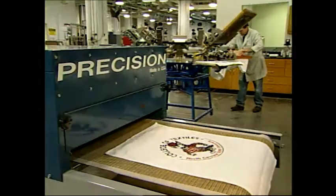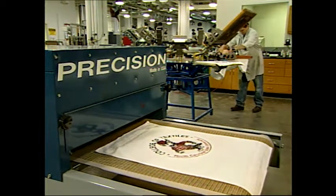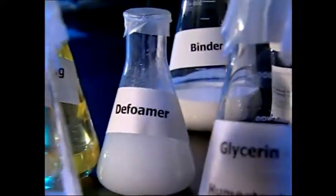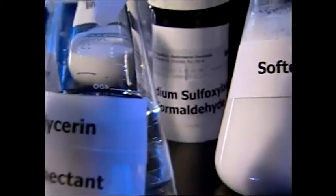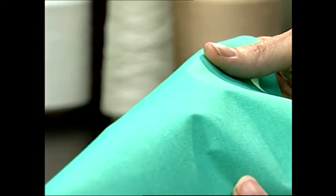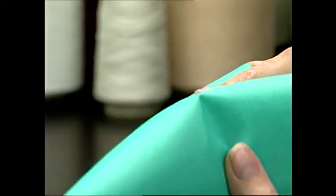Once printed, fixation of the pigment requires dry heat for a defined amount of time. The color fastness of pigments directly depends on the type and amount of the binder system employed. Binders can be water-based, known as latex, or solvent-based. These two types of binders vary widely in their stiffness. While greater amounts of binder will improve the color fastness, it may negatively affect the hand of the printed fabric. A balance must be achieved between the desired feel of a fabric and an acceptable level of color fastness.